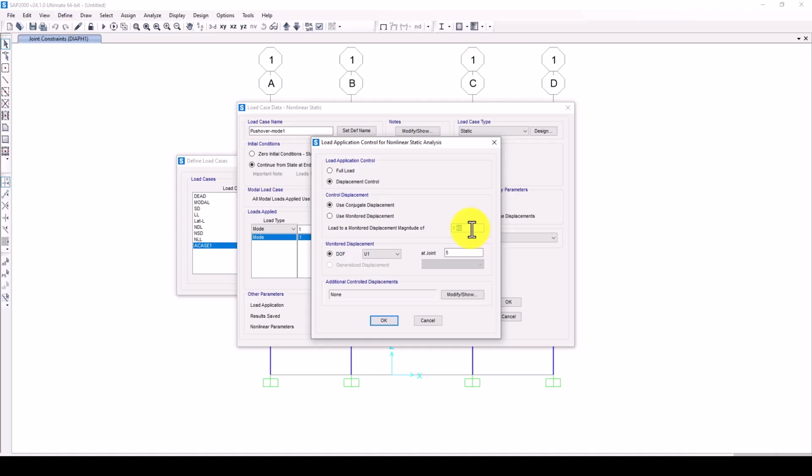How we can determine this one is not difficult. We use the yield point of that structure. So if it's a steel structure, the yield point is 1% of the drift. When it's concrete, immediate occupancy is 1, in another step is 1.5%, like this. But we want a larger displacement to observe how the structure responds during that large drift, 5% or 10%. So now let's suppose we want 10% of the structure height to be pushed, and then we want to evaluate how the structure responds.